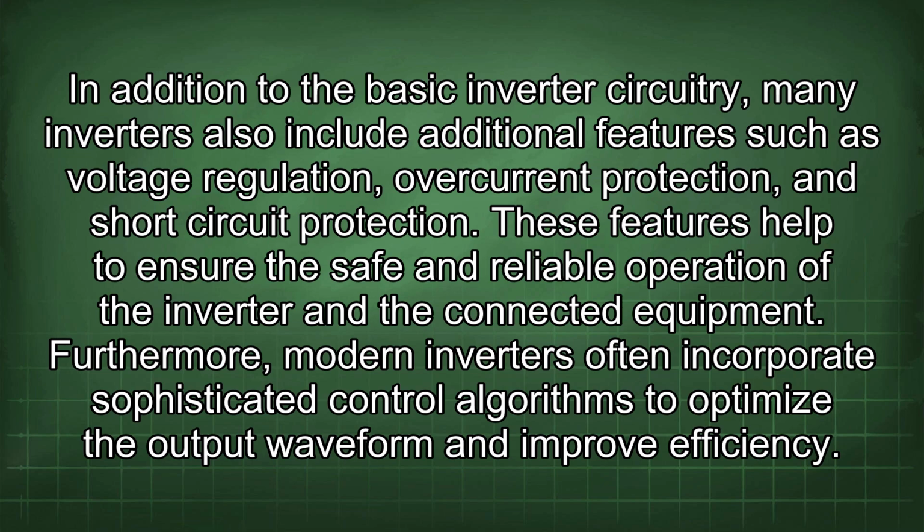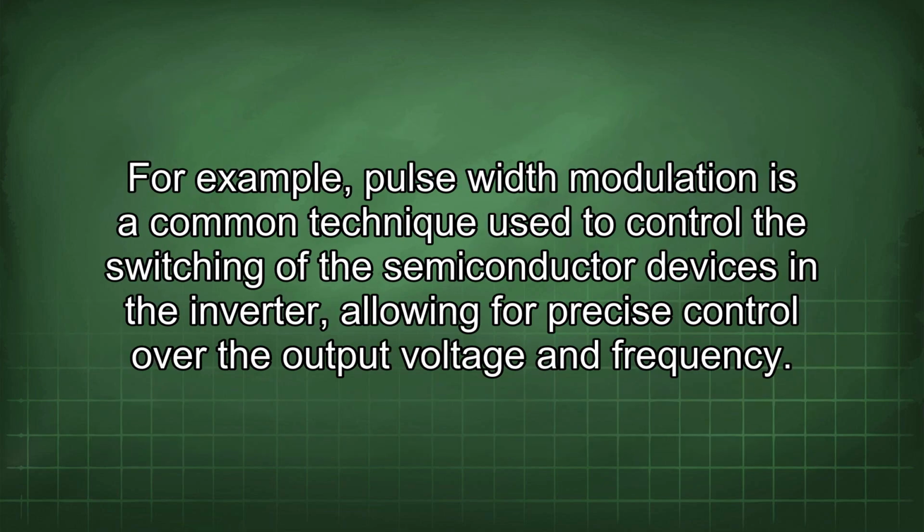These features help to ensure the safe and reliable operation of the inverter and the connected equipment. Furthermore, modern inverters often incorporate sophisticated control algorithms to optimize the output waveform and improve efficiency. For example, pulse width modulation is a common technique used to control the switching of the semiconductor devices in the inverter, allowing for precise control over the output voltage and frequency.